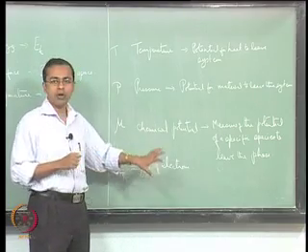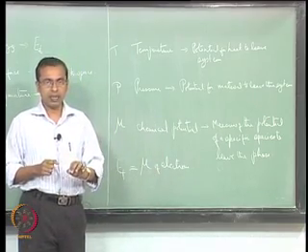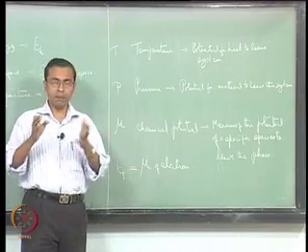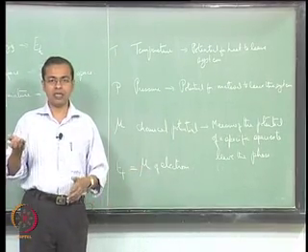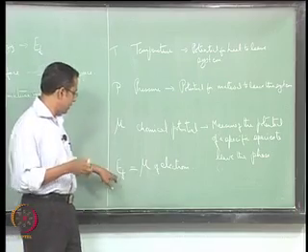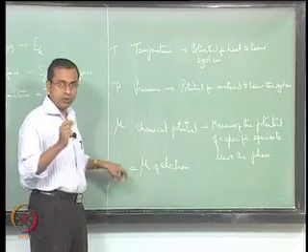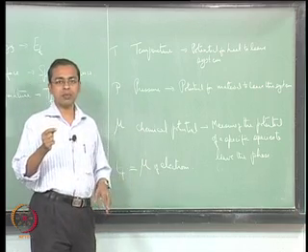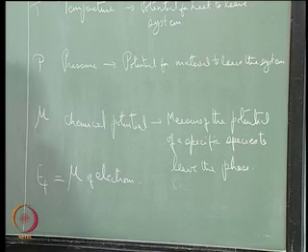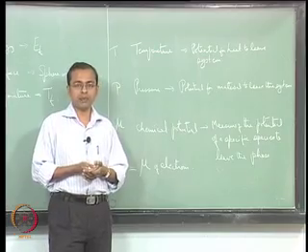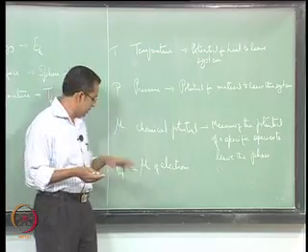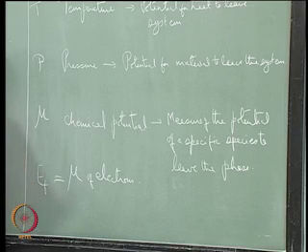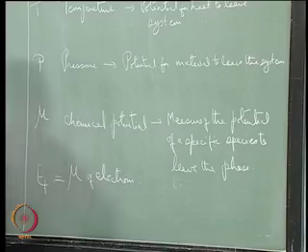So it is a measure of the chemical potential of electrons, and therefore in that context it is a very useful piece of information. It is not simply a definition of academic interest, it is a very useful measure because it tells us directly what will happen when you bring materials together. Even when you bring semiconducting materials together, when you make junctions of different materials, this is a very important phenomenon. The chemical potential of the electrons across those various junctions is important in the sense that there will be an attempt to equate those chemical potentials.